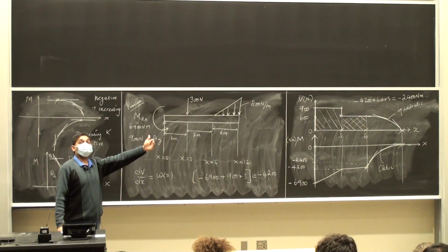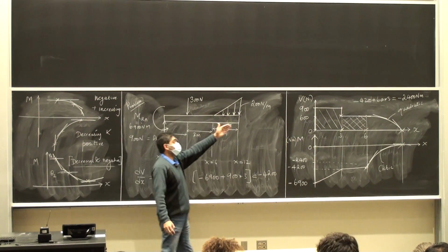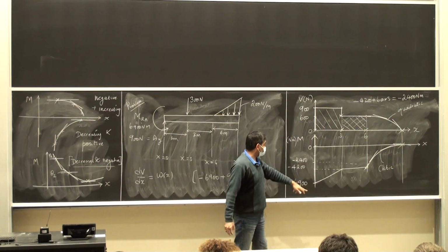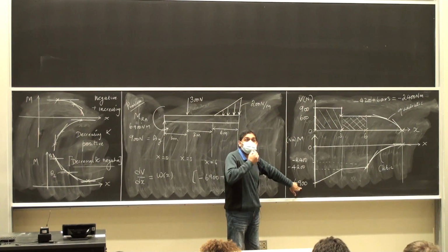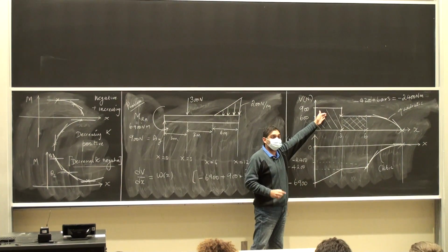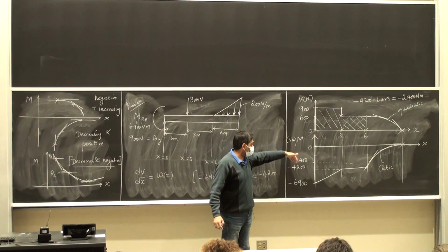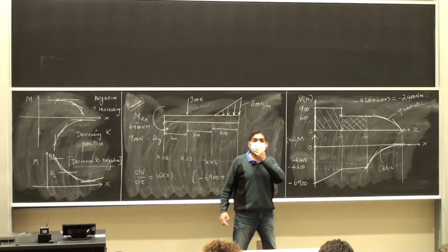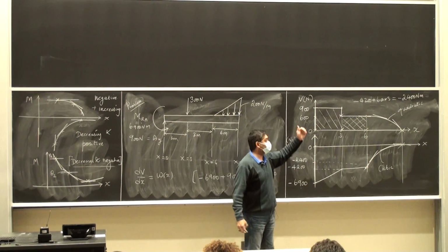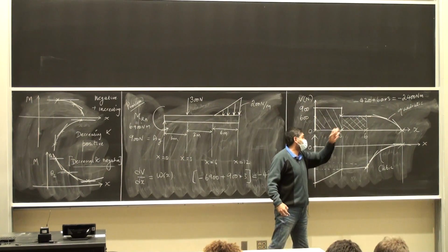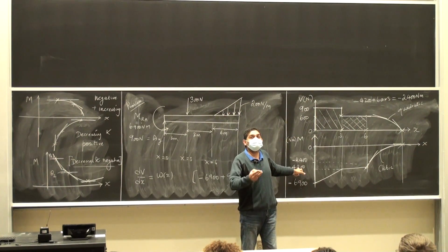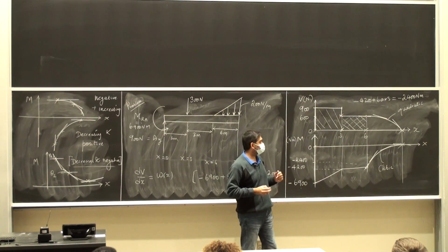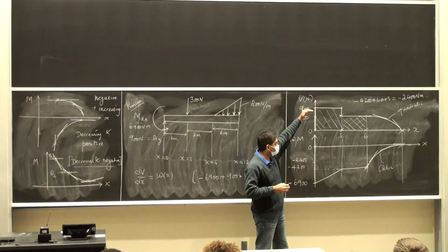Then the next stop, I have to look at the shear force diagram. Area under the shear force diagram has to be added with this value here. I'm adding it because the area is a positive area. That takes me to 1,400 negative. How do I go? Linear. Continue along the same line of thought. I have to take this area and add it to 4,200 because my shear force is in the positive x-axis. The shear force value is positive above the 0 x-axis.